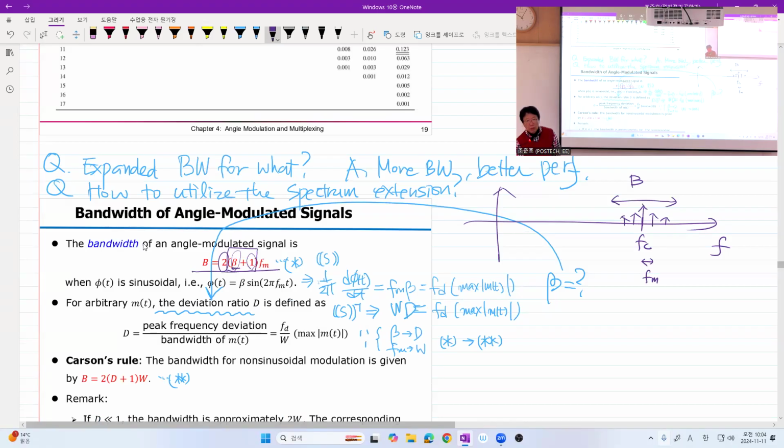And what is the beta? The beta is the modulation index we used in our simplified analysis, right? So beta appears here. Now, this is the start of Carson's rule. Carson not only just found, of course, this is a rule of thumb already, okay? So this equal is not equal, okay? If I were you, I would modify like this, okay? So it seems that the bandwidth of a real bandpass angle modulated signal, when we have a single tone, may be written in this way.